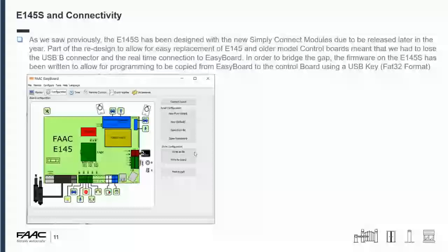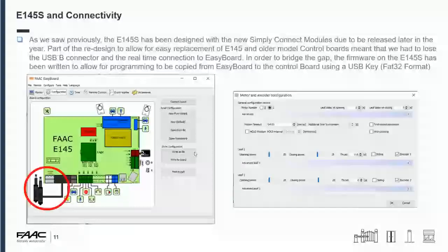But if you want to change the programming, this is a quick guide which I'll run through relatively quickly for you. You bring it up and you change your motors. This is also where you can have a mixed system. We have a few people that have done this already, where you have two motors and one of them is a sliding gate and the other one can be a swing gate. So you might have, say, a 42 PED, pedestrian operated with an encoder, for example. That is your pedestrian gate, where the postman goes through and all that kind of stuff. And on the other side, you might be using a sliding gate motor instead. All gets run from one unit. You have one set of safety devices essentially covering your system.